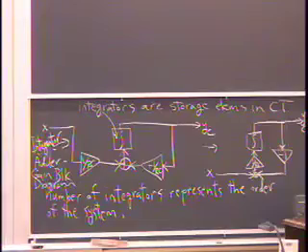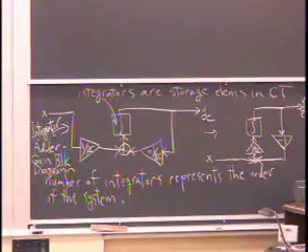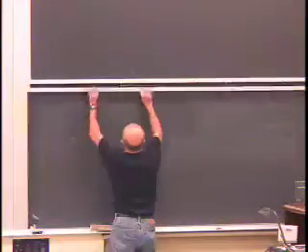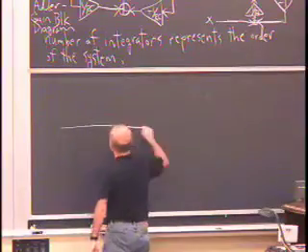You typically do not want to implement systems by differentiation. Can anybody guess why? Why do you not want to implement systems using differentiators in the real world? Think in terms of noise and accuracy. Yeah. You remember one of the things I said is real-world systems respond to the areas under the input signals. The areas under the signals are the determining factor. And integrating a function over some finite interval gives you a more accurate result.